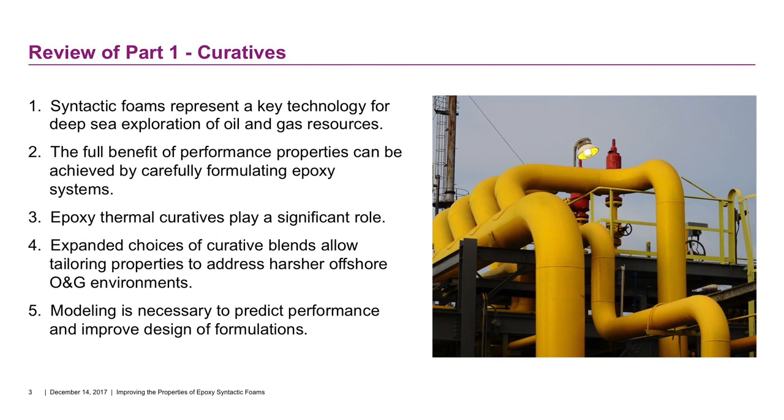From our standpoint, the use of thermal curatives is one of the strong levers to play this role, to show how the in-service properties can be altered through simple changes in your formulation. These curative blends, as you start to look at more of them and how they're blended together and in which ratios, really start to open up the idea of maybe tailoring properties of these foams, especially as you're looking at more extreme and more harsh environments for oil and gas exploration.